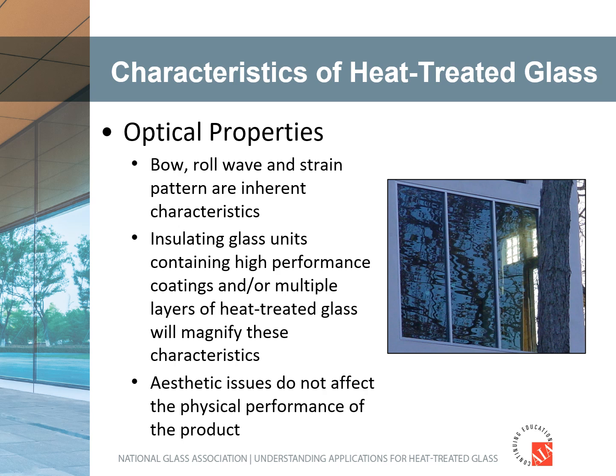Under certain conditions, the residual stress in the glass may become visible. This strain pattern effect, also called iridescence, is more noticeable in outdoor and automotive glasses at certain times of the day and viewing angles. Obviously, IG and laminated units that consist of multiple lights of heat-treated glass will have a tendency to magnify these undesirable optical properties if present, but it's important to note that roll wave and iridescence are strictly aesthetic issues that do not affect product performance.